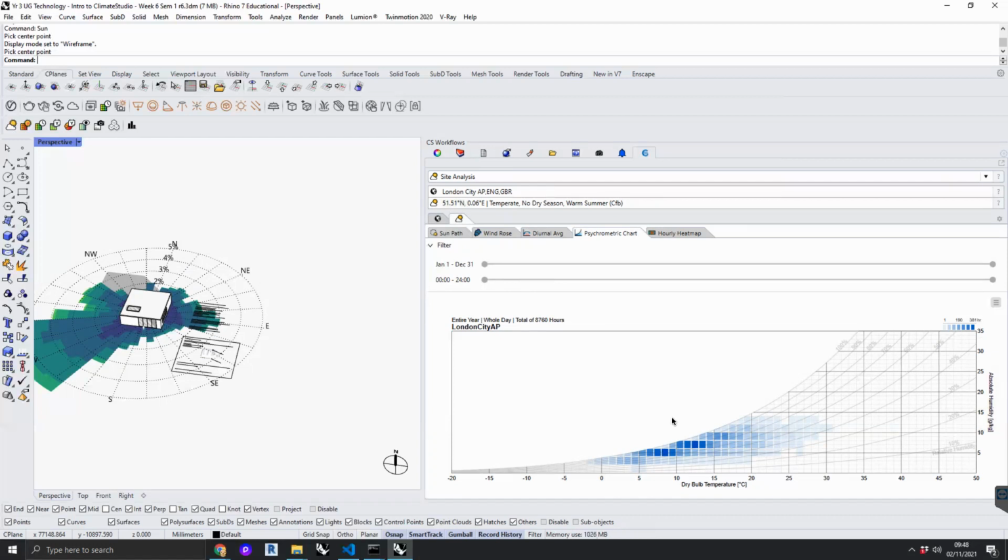If you live in a climate which is super humid, super saturated with moisture, then what happens is you sweat a lot, right? I've found this. You realize your body is producing all this moisture, but it's not evaporating because the air is already saturated with moisture. There's nowhere for it to go. So using evaporative cooling in your humid climate is going to not be as effective. In the same way, your body is going to try and sweat, but your sweat's not going to go anywhere. You go to a hot but dry climate, your sweat, it's gone away in an instant.